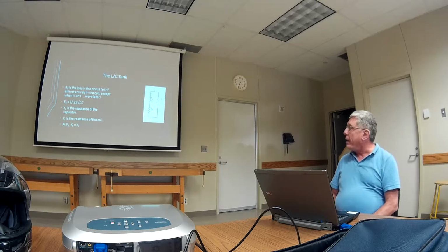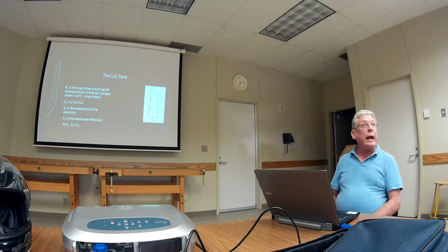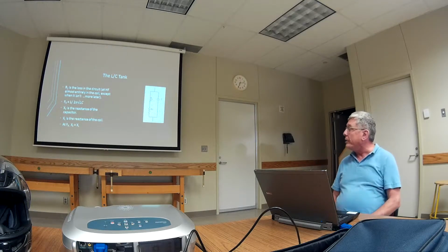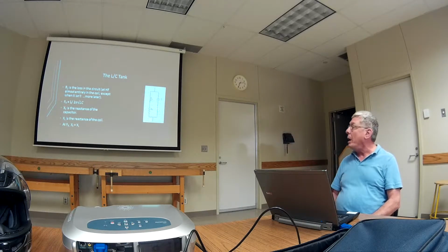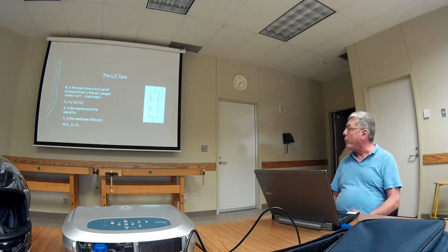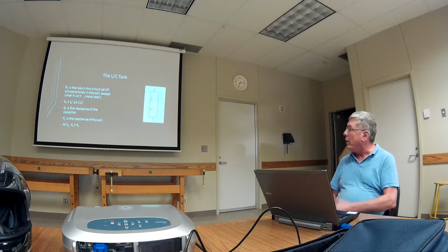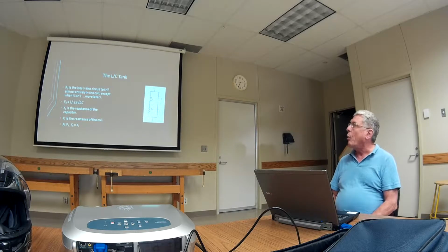So here's the tank. With an inductor and capacitor, we're going to use a parallel resonant tank, and that R sub C is the loss in the tank. In other words, you could hit a tank like this with a pulse, and if it were perfect, it would just ring infinitely, forever. But every time current makes a trip around the tank, we lose a little bit of energy, and that's what R sub C is representing. And at high frequency, most of that loss, or maybe almost entirely, is in the coil, except when it isn't, and we'll talk a little bit about that later.